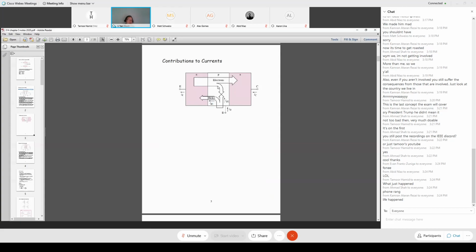There's some part of the electrons injected in the base that recombine with holes, what we call electron-hole recombination. This process unfortunately exists, but we don't want that to happen. So we want to make this process as minimal as possible. So what we usually do is make the base region very thin, so they don't have much chance to recombine. So electrons inject in, then end up at the collector. Any questions?